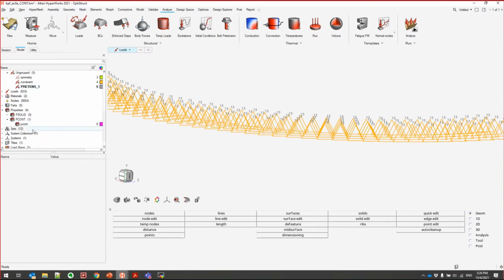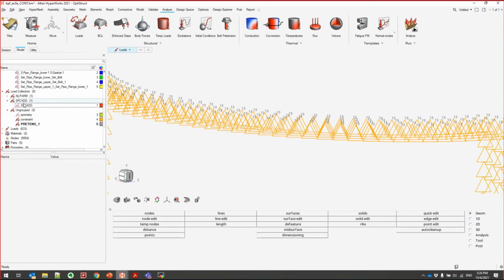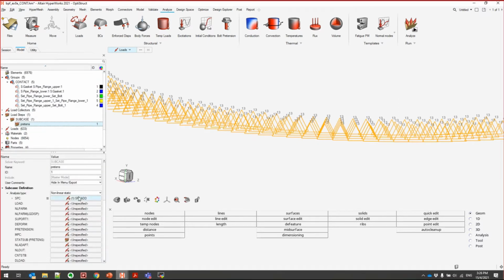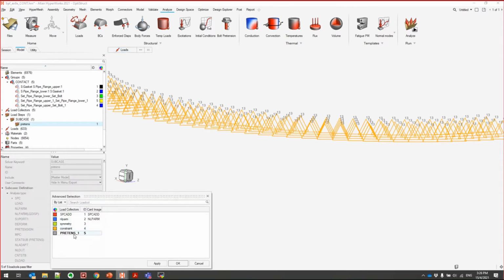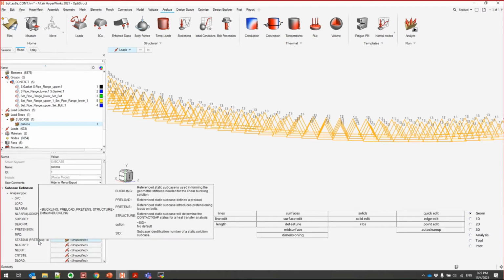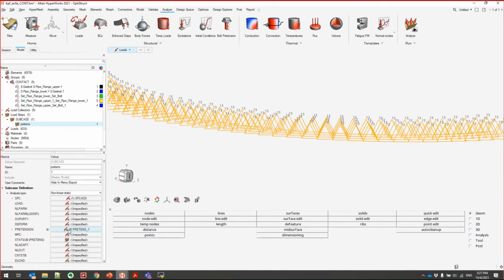Okay, so go back to my load step. Load step, sort my name. Okay, load step, pretens, SPC add. There's no load because I apply my pretensioning here. So it's a pretens, so you need to define this here. This is a pretensioning step, solely pretensioning only. Okay, step is meant to be referred. So this is the first step where I apply the pretensioning. So this is used later on, not now. You just need to define pretens here.